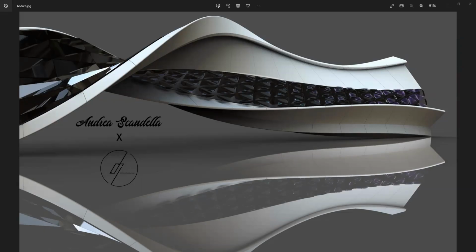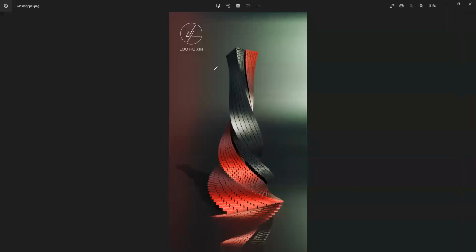Another interesting example I like by a participant is this one. Again, same exact algorithm, but this time instead of using a curve as a base geometry, the participant has used a grid of boxes. So you start by creating a grid of boxes, you move it to create multiple arrays of boxes in the z-axis, and then you scale it and you rotate it and you get this kind of form. Obviously, you don't do a loft at the end because you have boxes and not a curve. But you use the same algorithm with a slightly different initial geometry. Instead of a curve, you use a solid and it gives you something really interesting like this. So I think this is also another interesting experiment done by the participant.